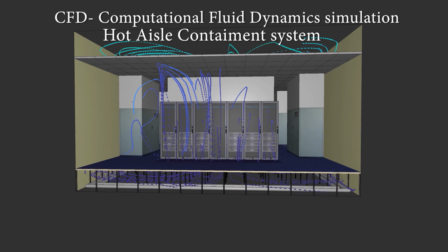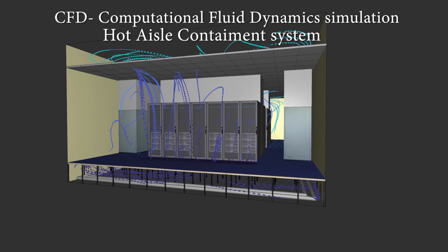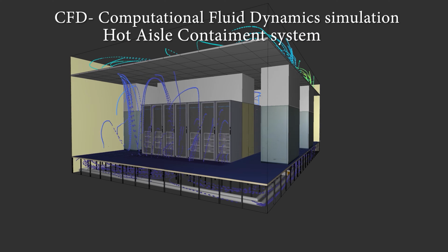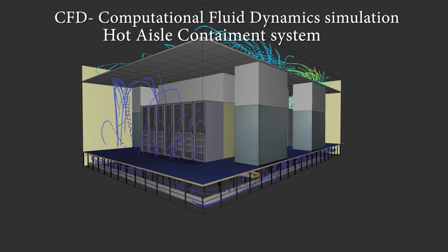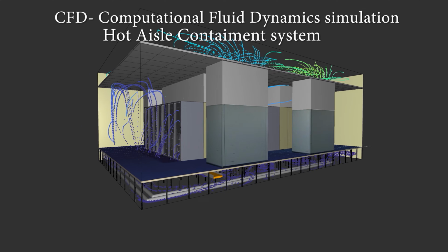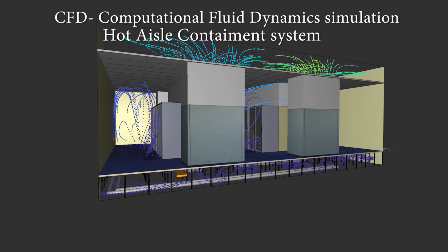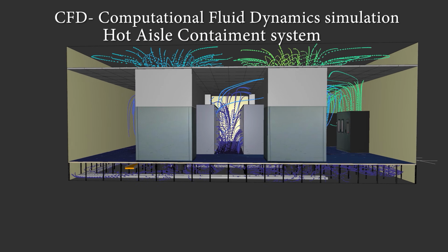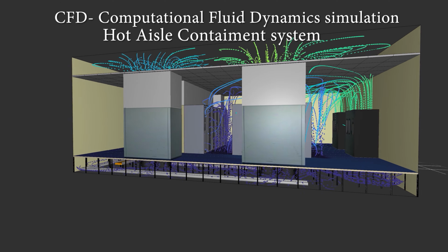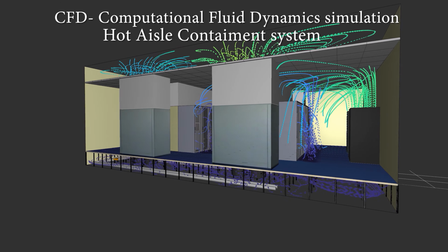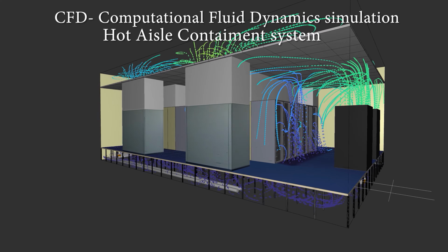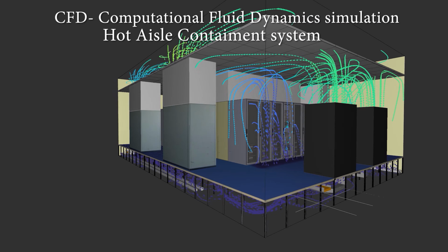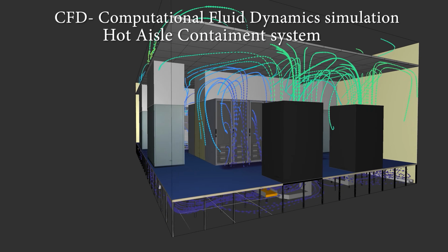Exhaust air returns to cooling units at high temperature, thereby optimizing efficiency of the cooling unit. Hot aisle containment is typically a more expensive solution since it requires a false ceiling. Here, the hot aisle containment prevents hot exhaust air from mixing with the air in the rest of the data hall. This results in lower average temperatures across the whole room, at the expense of a slightly less consistent air supply to the cabinets.